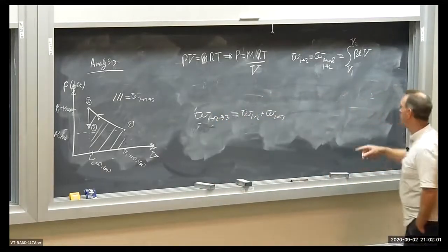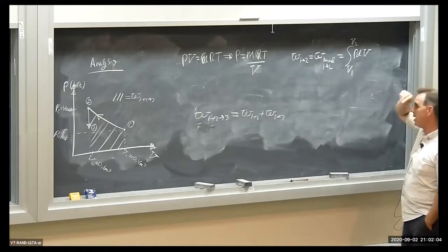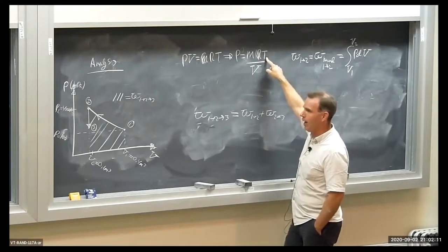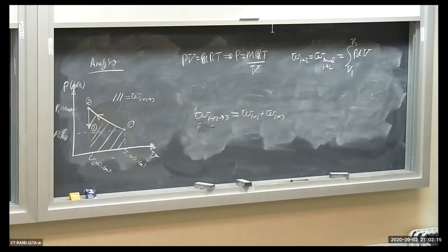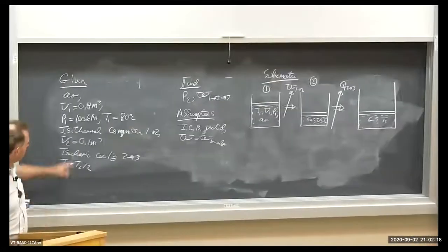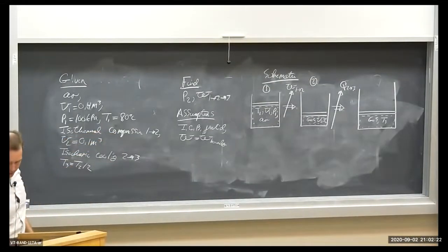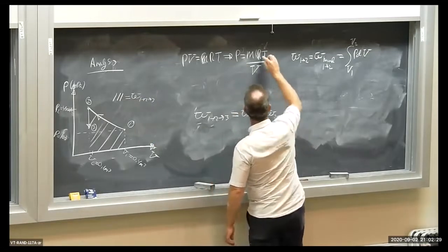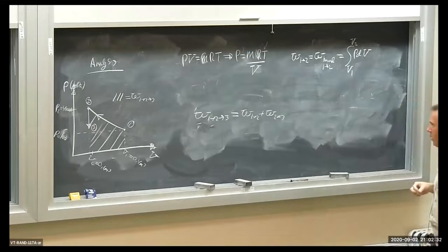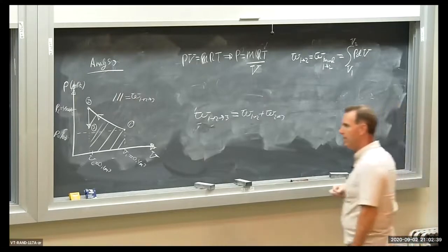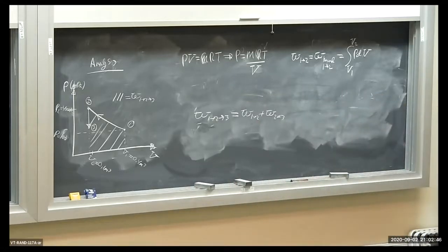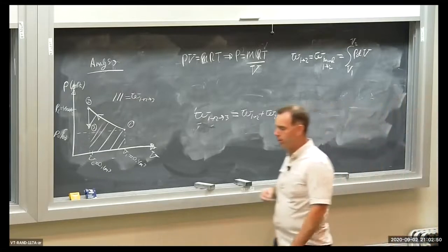Now, I could substitute that into this integral here. The only little thing is, how do I know what temperature is over the process 1 to 2? It's an isothermal process, and I get a temperature of 80 degrees C over here. So here's temperature T1, just convert that into Kelvin, and I could immediately plug it into the ideal gas law. So I do know the temperature. The gas constant, I could get it. But I don't know the mass. I could calculate the mass. I know pressure, temperature, and volume at state 1, so I could use the ideal gas law to crank out the mass.